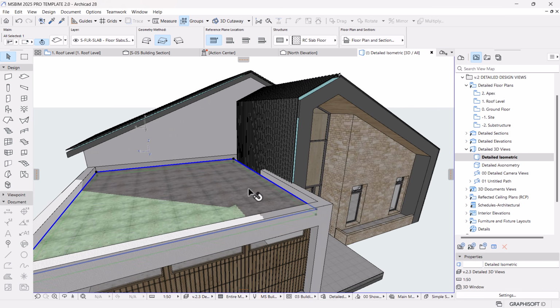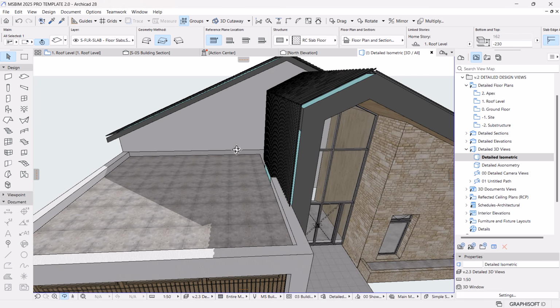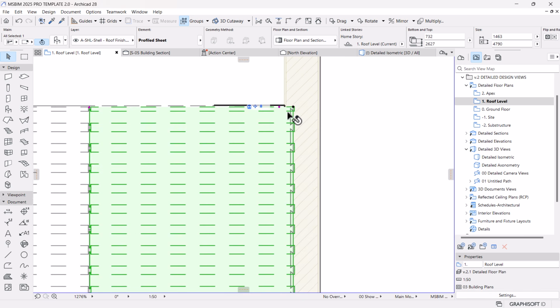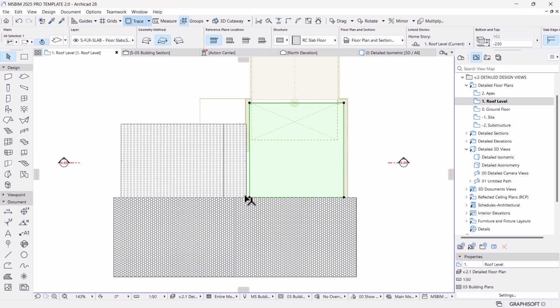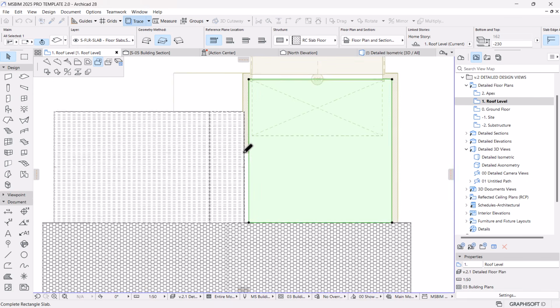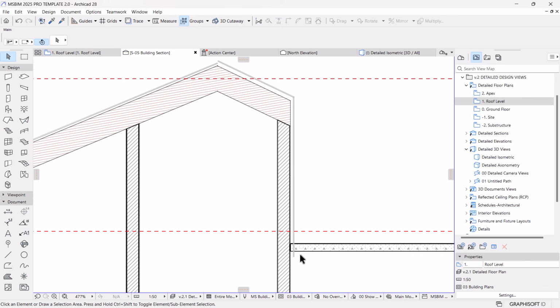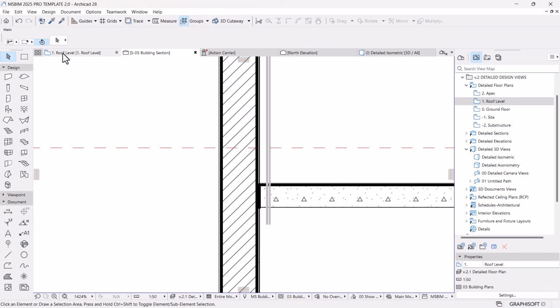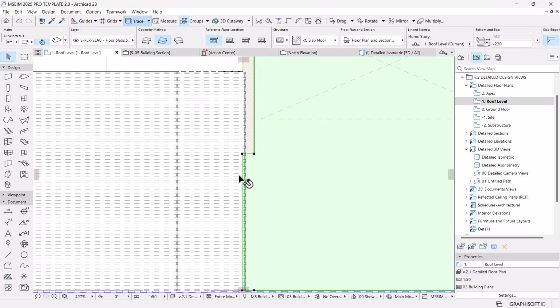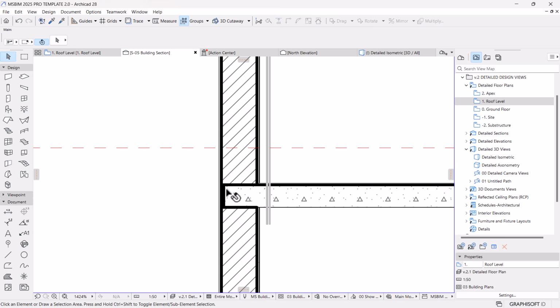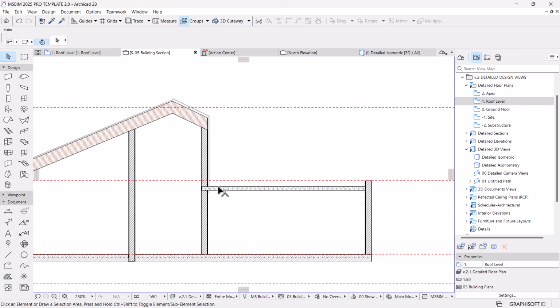Alright, then this slab should, let's do it on 3D. I'm going to add a polygon of this to there, so that when you cut a section, the slab should go all the way, not stopping on the edge. So I'm going to offset this by the thickness of the wall so that it can, yes, okay.